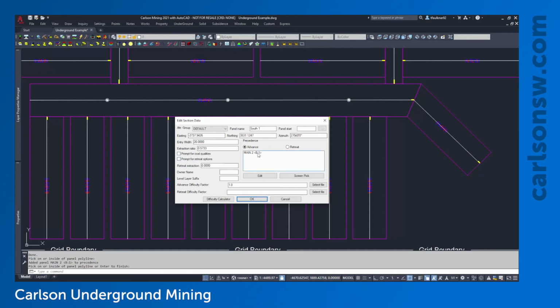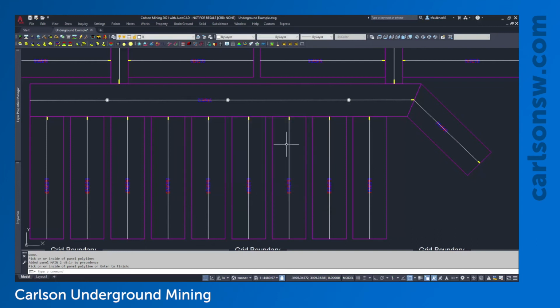Now, just to show the other names of this panel that's been subdivided, I'm going to click on this edit list, and I can see it's referring to 4 sections. So again, this is main 2. The B stands for beginning up to the first pinpoint. This would be pinpoint 1 to pinpoint 2, 2 to 3, and pinpoint 3 to the end. So that's just the way the program will present those panels to us whenever it comes to the timing.